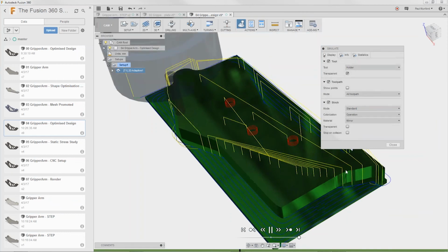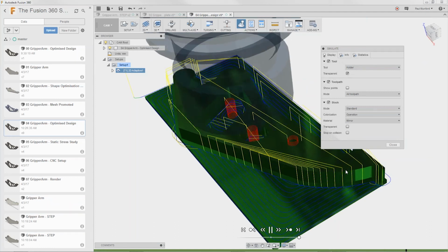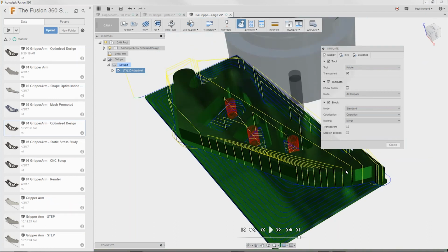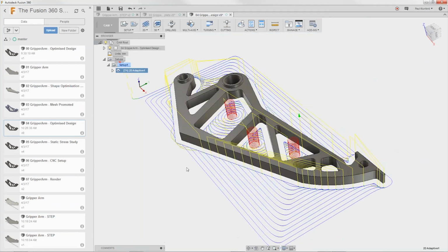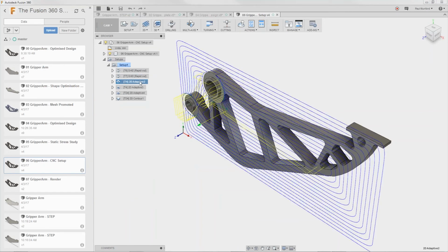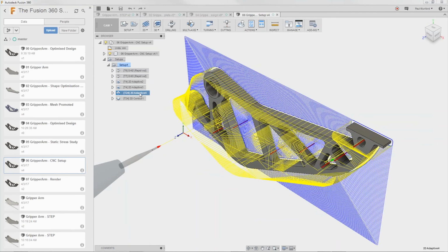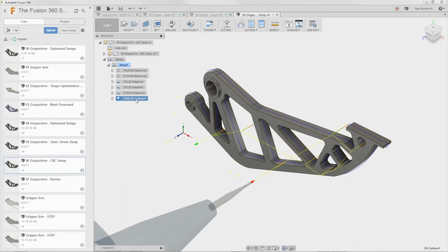So here we are. This is the calculated toolpath that it can do with that size of tool, and we can simulate this. If I come up here and click on simulation, we can click on play, and it's just going to show us. I'll turn on the stock so we can see how that will work, and I'll speed this up a bit so it's a little bit more useful to look at. So we can simulate this, which means we can optimize it. We can make sure we're running our tools in the best possible order to make sure that we are getting through this as quickly as we can, whilst making the best use of the tool and reducing machine wear and so on. So I'm going to pick close there,